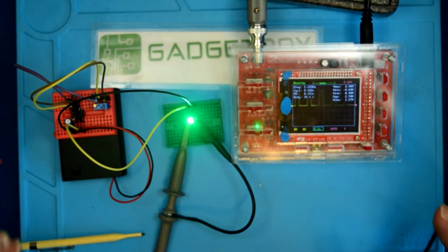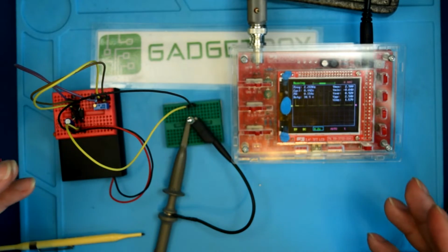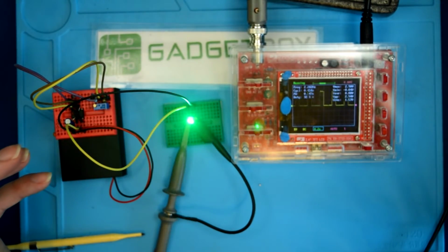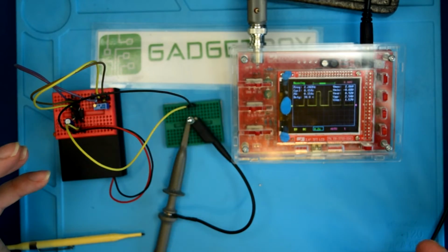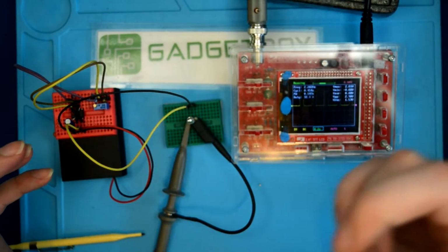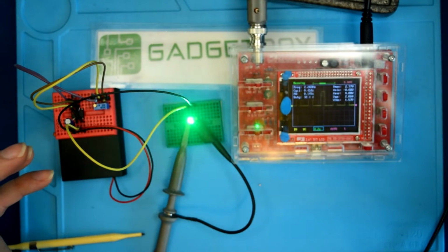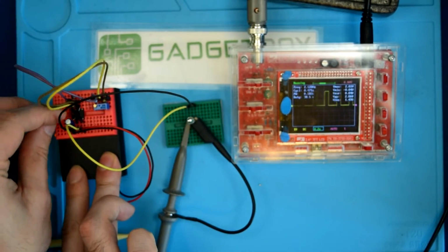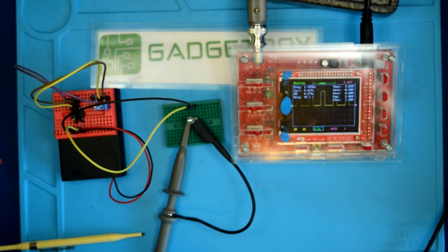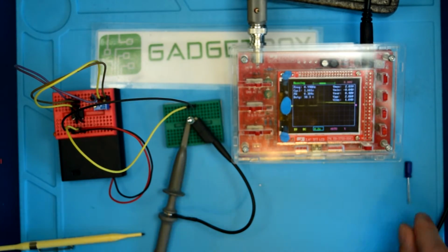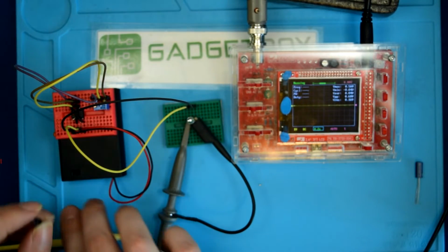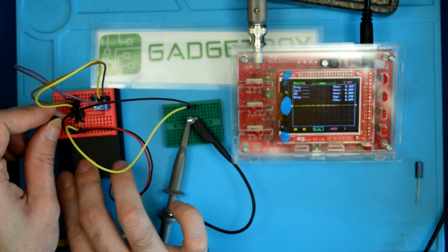Anyway, so pulse width modulation with LEDs, especially for lighting, is a difficult concept. Well, it's not a difficult concept, it's difficult to implement well. That's why I use a linear driver for these LEDs, because we don't run into problems. So what kind of problems do we see with pulse width modulation? Well, let's pull out this capacitor, and let's go for a higher value capacitor. We're going to increase the frequency of the flashing.